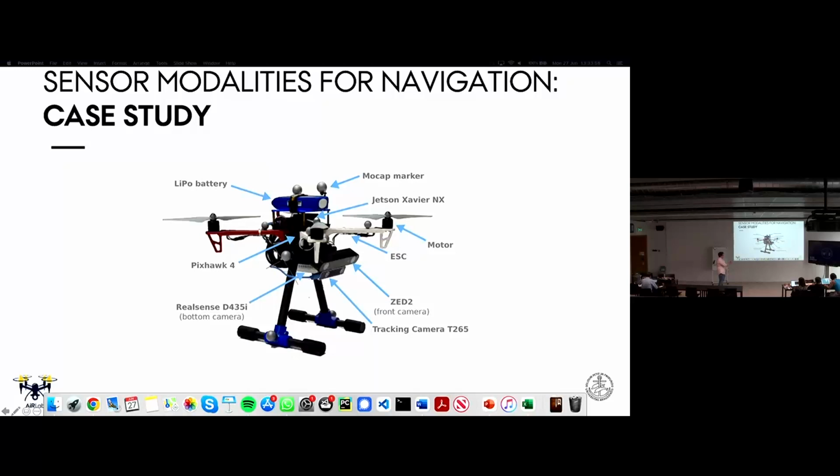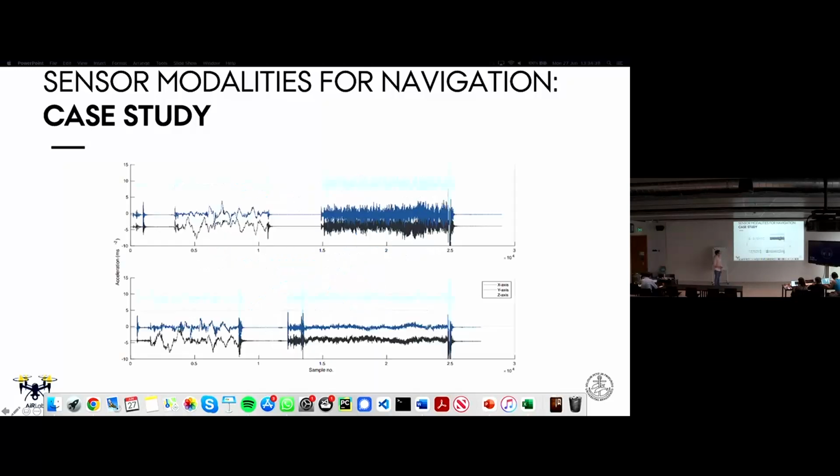The idea here was that we were using a stereo camera to get depth information. A number of different SLAM algorithms use stereo implementations of this, and you can track the features through the space. The problem, however, was that this camera uses what's called a rolling shutter. You can imagine that the shutter, the refresh rate of the image, rolls around in sequential lines across the screen. And when that was happening, the engines were giving quite high frequency vibrations. I'll show you here. This is us carrying the drone.